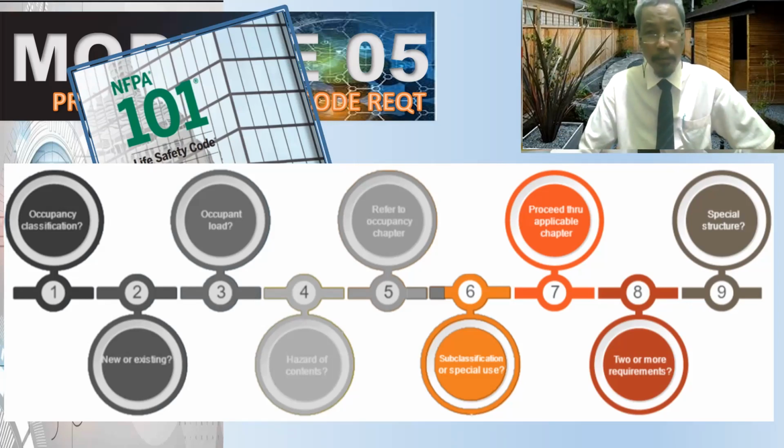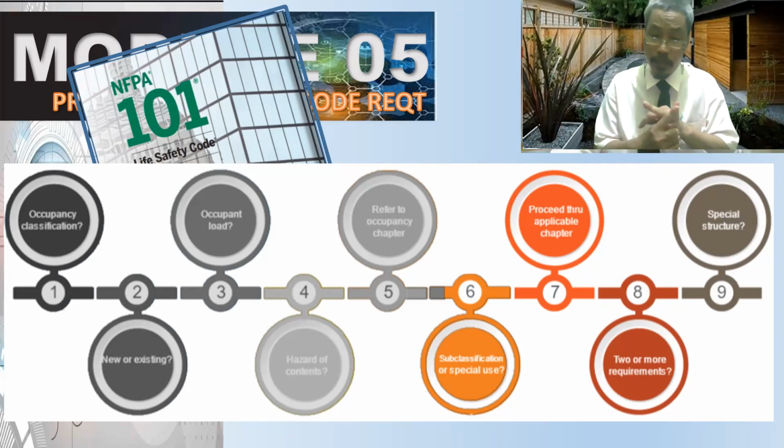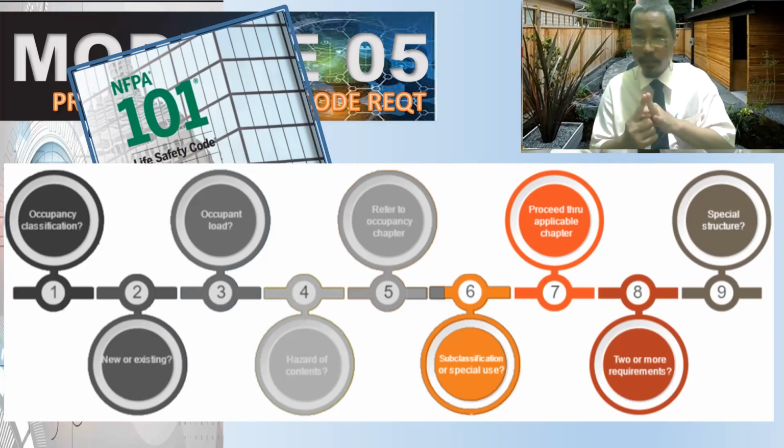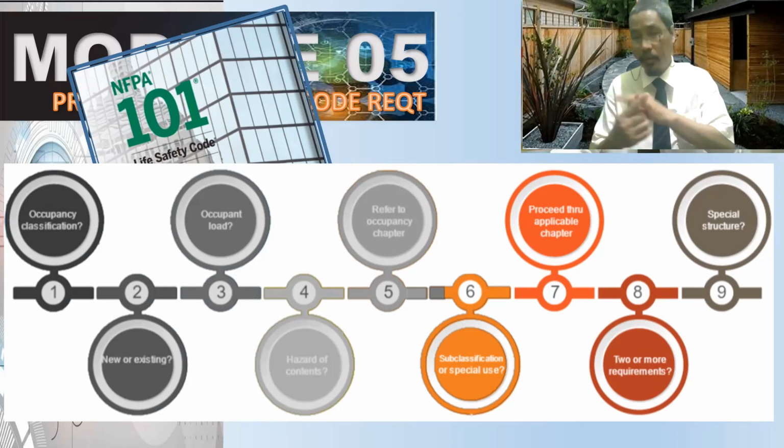No need to add. If one provision says 2 sprinklers, another one 3 sprinklers, another one 3 sprinklers, you don't need to put up 8 sprinklers. You don't need to add. Just use the most restrictive one, and never use the least restrictive one or the average. Only the most restrictive one.